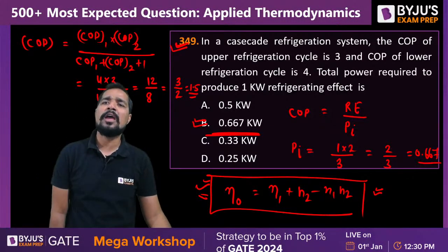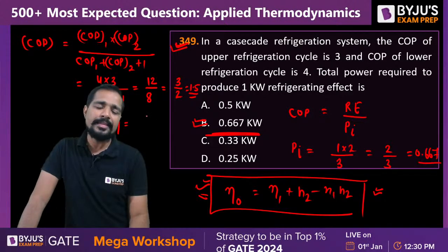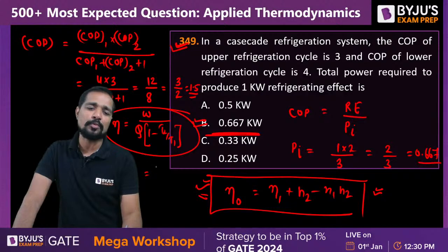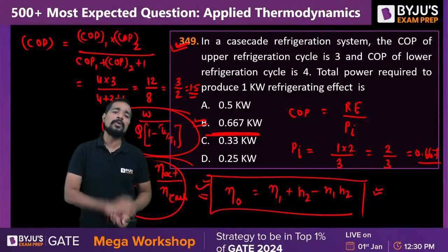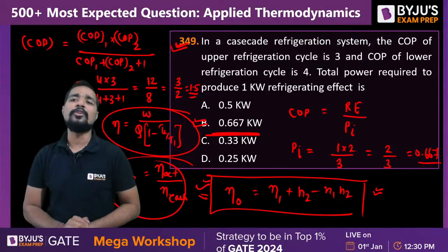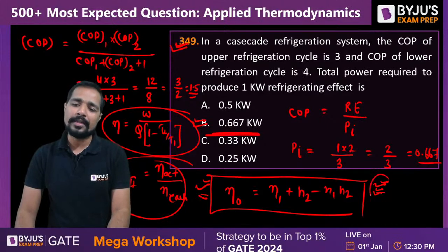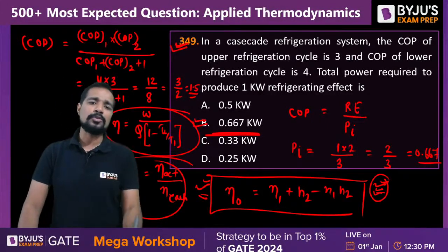Sir, I saw that for efficiency. No. Efficiency formula, whatever you have seen now in second law of thermodynamics, my dear. Let me tell you, in this case, the second law of thermodynamics, we write W divided by heat supply, my dear, 1 minus T2 divided by T1. This is the formula. This second law efficiency formula is the actual efficiency divided by efficiency of Carnot cycle. Okay, this one. This is the second law efficiency. So this formula you have definitely seen when you are dealing with the second law of thermodynamics or second law efficiency, my dear. Clear? And yes, this topic I have already taught you in second law of thermodynamics or Clausius inequality law. So definitely in that portion you have also seen the same topic.